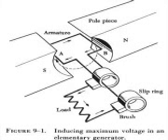The diagrammatic and schematic illustration of a compound wound generator is shown in A and B of figure 9-17. If the ampere turns of the series field act in the same direction as those of the shunt field, the combined magnetomotive force is equal to the sum of the series and shunt field components.